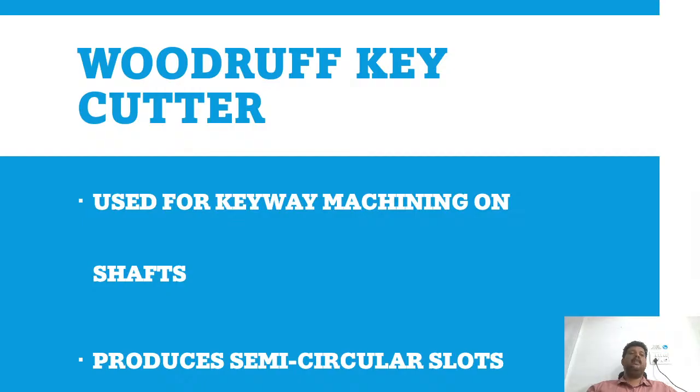Now, let's move to the next important tool, the Woodruff key cutter. This tool is mainly used for machining keyways on shafts. Now, what is a keyway? Whenever you have a shaft and you want to fix a gear, pulley, or coupling on it, you need something to lock them together so that both rotate together. That locking element is called a key, and the slot where this key sits is called a keyway.